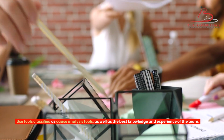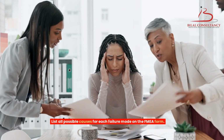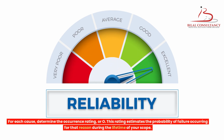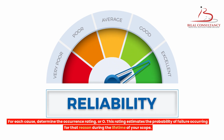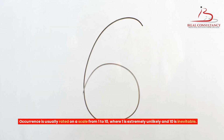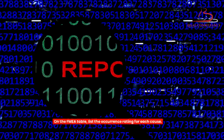For each failure mode, determine all the potential root causes. Use tools classified as cause analysis tools, as well as the best knowledge and experience of the team. List all possible causes for each failure mode on the FMEA form. For each cause, determine the occurrence rating, or O. This rating estimates the probability of failure occurring for that reason during the lifetime of your scope. Occurrence is usually rated on a scale from 1 to 10, where 1 is extremely unlikely and 10 is inevitable. On the FMEA table, list the occurrence rating for each cause.